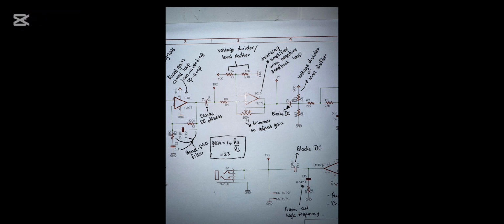P1, the 100 kilo ohm trimmer potentiometer, controls the feedback signal, and it can reduce the overall gain of the amplifier. R9 and R10, also found as the level shifter, provide the voltage and the virtual ground for the waveform, as in stage 1. This stage can be used to stabilize the waveform and adjust the intensity of the waveform.